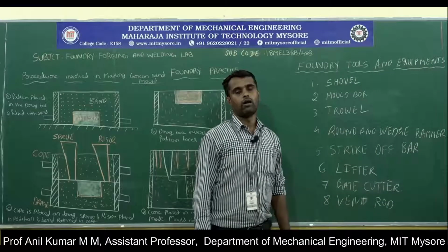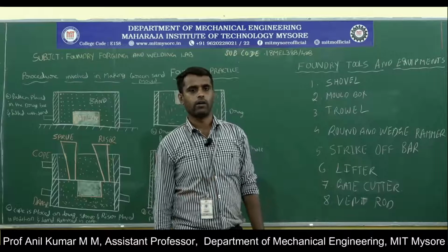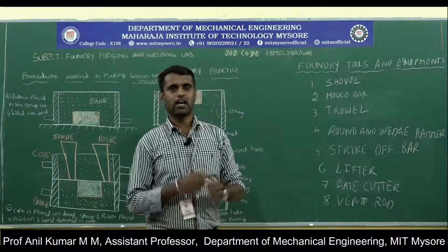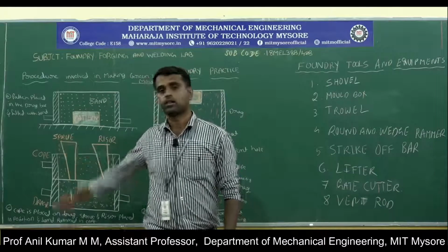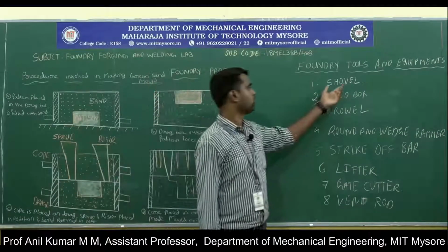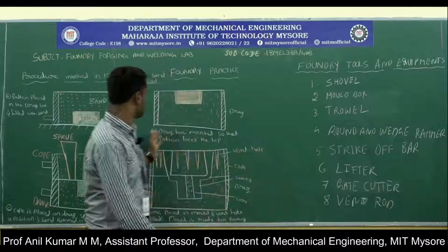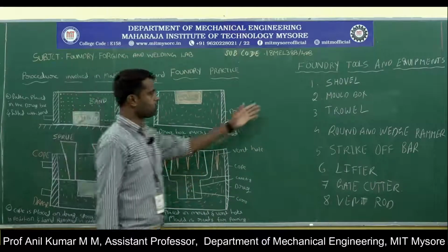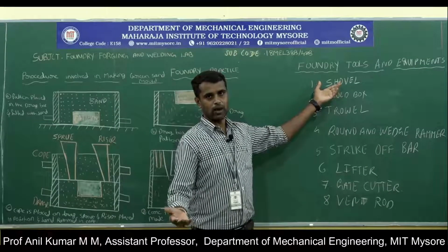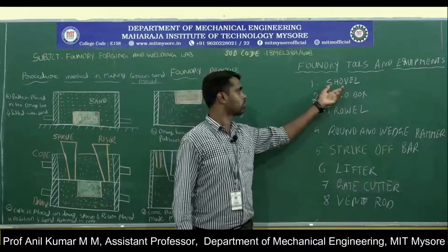Okay, the shovel is a steel pan attached to a long wooden handle, a wooden rod. This shovel is used for mixing and reconditioning the green sand, and also to transfer the sand from the container to the mold box. Initially you have to prepare the sand in a container, so to transfer the sand from the container to the mold box, the shovel is used. It is a steel pan base with a long wooden rod attached to it. That is called the shovel.